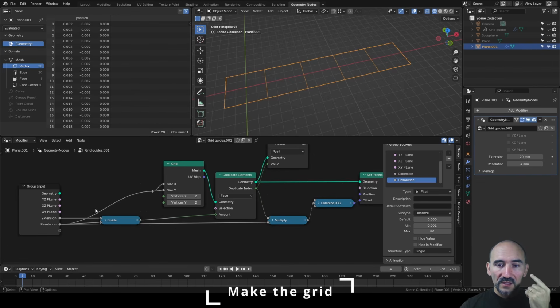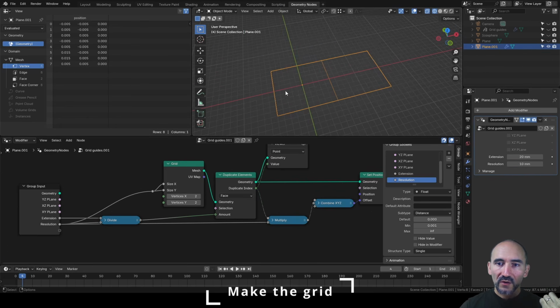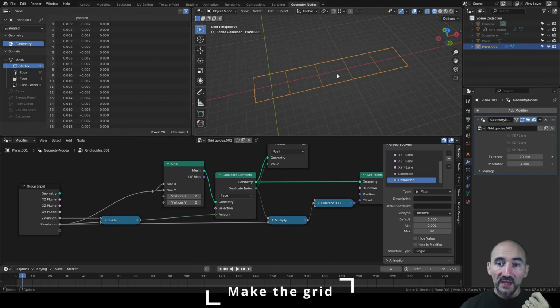So if the division of these 2 parameters is an even number, it's perfect, because if I set here 5, we have the center here on this edge, and from here the system starts to make the squares on one side and the other side. If I set 10 millimeters, perfect, we have only 2 squares, but the center is always on this edge. But if I have 4 millimeters, we have a problem.